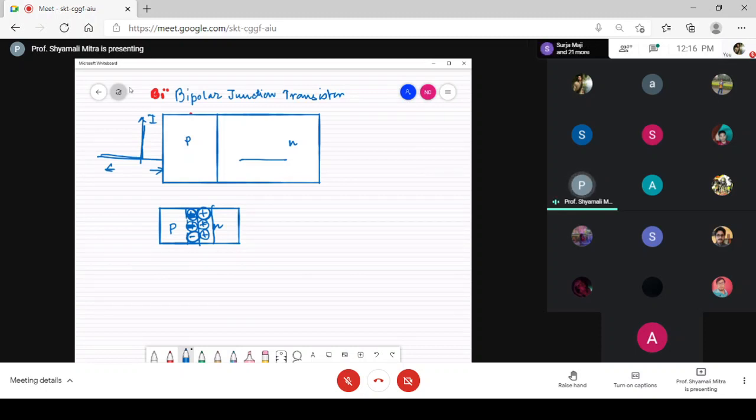These ions are relatively heavy, as in the previous discussions we have argued that they consist of the nucleus, electrons, protons, and are also bonded with the neighboring atoms with various bonding arrangements. So they are pretty tightly bonded. As a result, they cannot move, and they form this depletion region, due to which any further movement of the majority carriers is restricted.